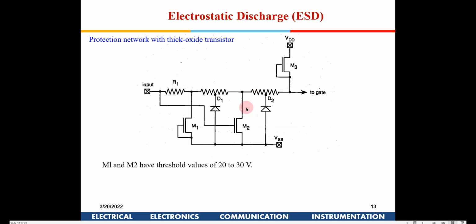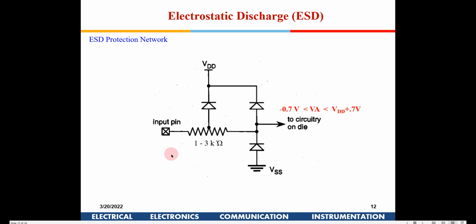So this is one more circuit. Are these removable circuits? No. When you design a circuit, these are IO pads, which are generally given by the manufacturer itself. The IO pads will have this, and there will be other parts. This is a small portion of the IO pad. Those IO pads will be given by the manufacturer, the layout as well as the schematic.